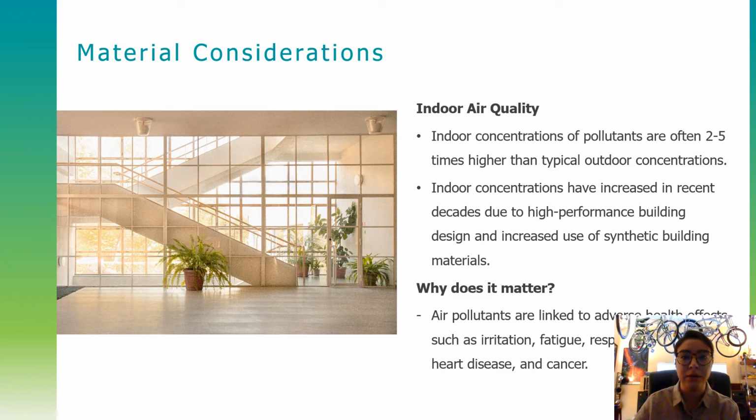For example, you want to improve your air tightness of your structure to reduce heat loss, prevent moisture infiltration. And a lot of times in these airtight designs, it's really important to maintain proper ventilation because that's kind of an afterthought of post sealing the facade.